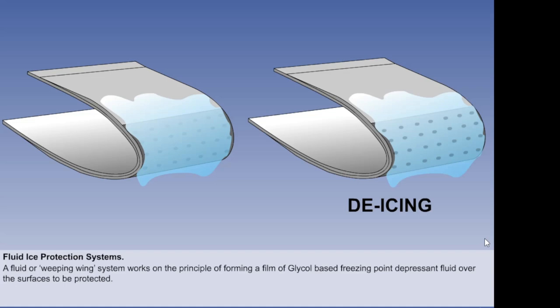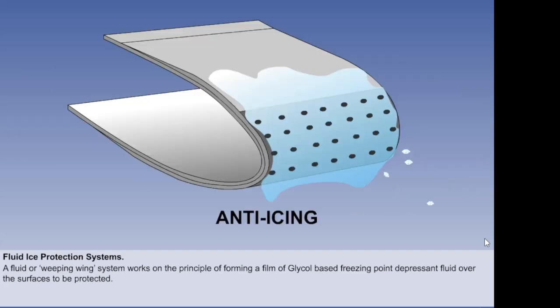This film of de-icing or freezing point depressant fluid combats ice formation by both melting the ice and by preventing adhesion of any ice crystals. Hence, the system can be operated in a de-icing or anti-icing mode.